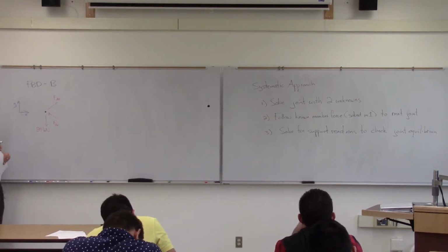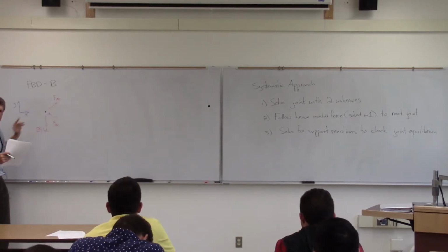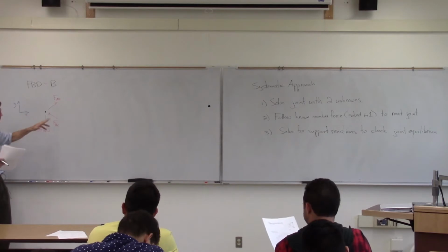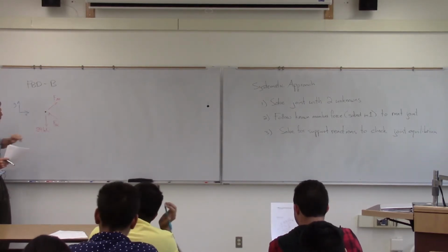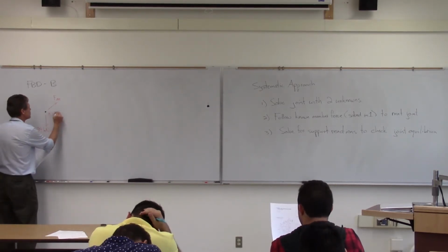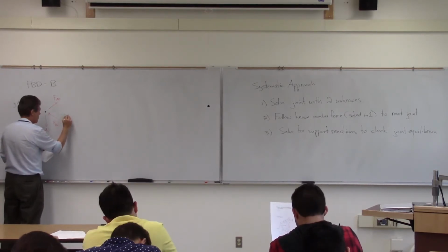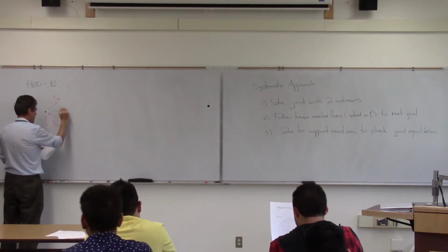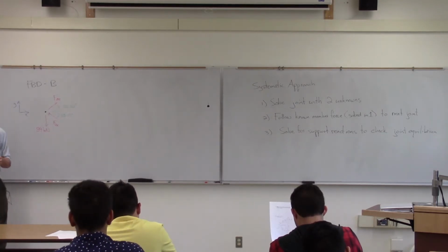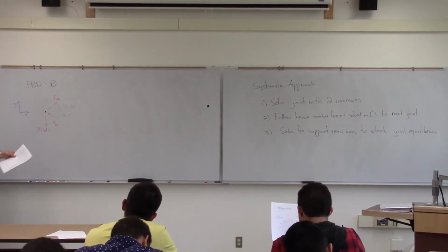So I put in my forces, and I just choose arbitrary directions. I choose arbitrary signs. The directions are actually defined. So they're going to be pin to pin, basically like that. So the direction's defined. That's why there's only one unknown in there. But I'm going to choose my sense. It'll either be that way, compression or tension. And then the other thing I need is my dimensions.